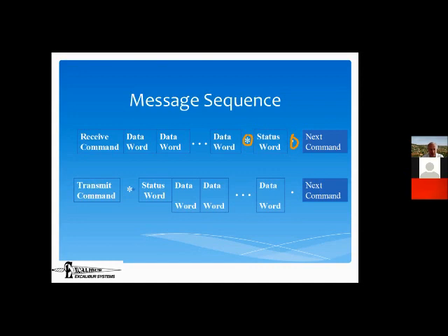because of the processing that the RT has to do once it gets the command word. First of all, it can't even start processing until the command word is completely finished, because it has to know if there's a parity error. If there's a parity error, it's not allowed to do anything. And then after that, it has to figure out, first of all, is it a legal command word altogether? Once it's a legal command word, he has to look at the RT address and see, does this RT address refer to him? If it does, he has to look at the TR bit and decide what he's supposed to